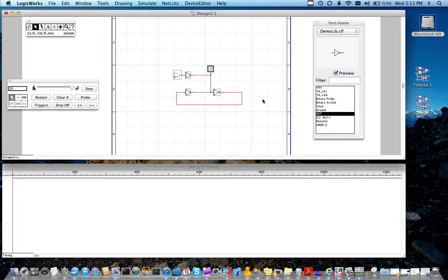So we need to do one other thing here. We'll move that along. And just as we did in one of the earlier circuits, we're going to put down a pull-up resistor. Rotate it with the arrow keys and put it there. And the +5. Okay, and I think what we'll do here is name this one clock. And we'll flip that, and we'll see we've built ourselves a clock.